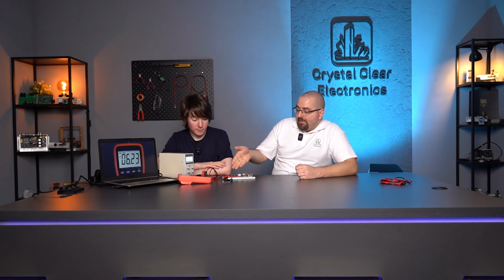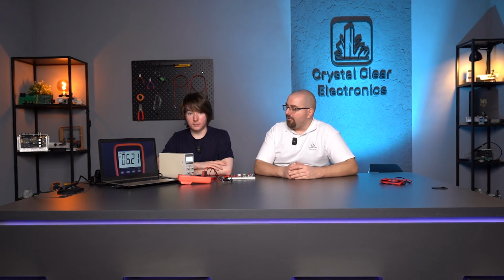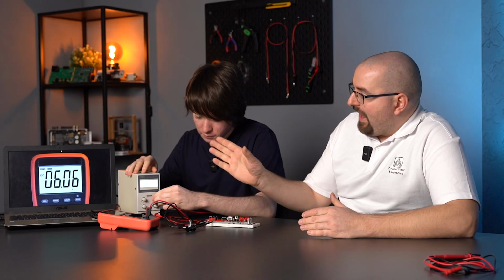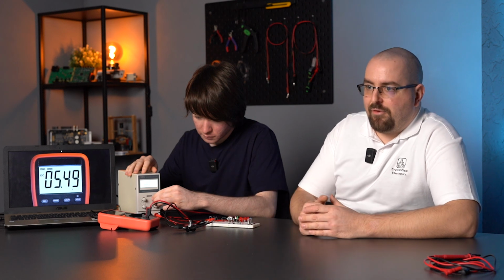You can see that we've put in the load resistor and we're still at the stable 6.2 volts. However, if Marcell starts to reduce the voltage slowly, you can see that now, at 13 volts, the voltage is dropping. It's dropping very rapidly. Now we're around 11 volts and we are very far away from the 6.2 volts that we were expecting. At least it's sure we consumed more than the calculated 1.8 milliamps, so the stabilizer can no longer operate reliably.